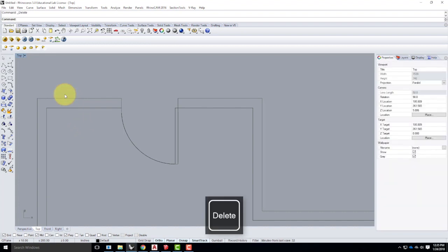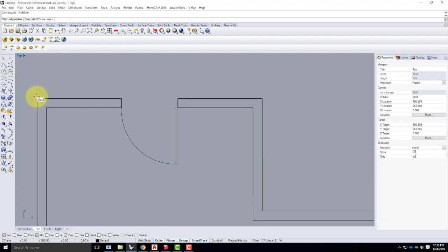So instead of doing that, we're going to pick the Polyline tool the same way, and we're going to move our mouse over that corner. And as I move over the corner, we get end. But see, I also get a little white dot that stays on the end there. Okay, I haven't clicked at all. I'll then move my mouse in this direction, and now the white dot turns blue, and I get a white line that's running perpendicular.